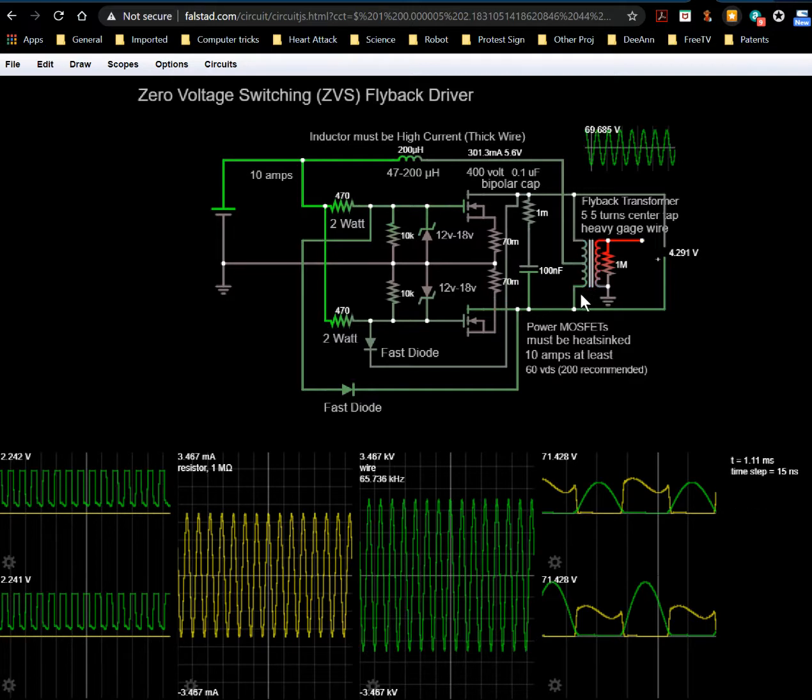That's what keeps the current at zero. It's like you have one battery opposing this battery. But eventually, based on an LR time constant, current does start to flow, and as it does, this voltage starts to decrease.